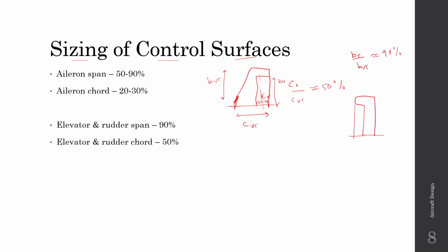So this is a rudder, and this entire thing moves up and down about this hinge line. The hinge line is over here, and in this location some heavy mass is placed. This mass helps us to balance the control surface such that a lot of force is not required. So it doesn't take a lot of force to actuate this control surface. So this tip location may be used for this purpose.